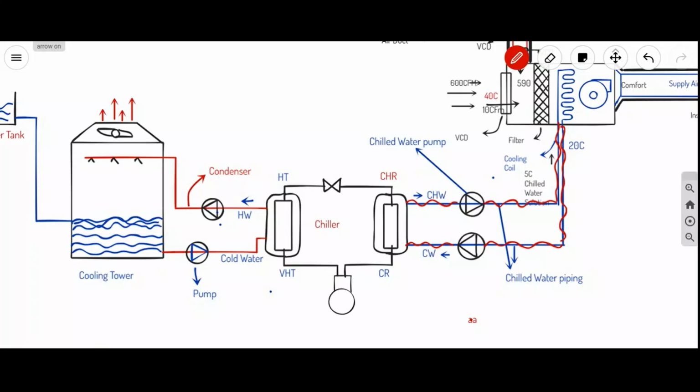Hope you are clear with this, sir. Yes. Is this PPR or can UPVC be used? Are these pipes PPR or UPVC or CPVC? Pipes are not CPVC, sir. Pipes are made with GS, galvanized steel, or mild steel. So iron pipes. Why? Because they are working with high pressures.